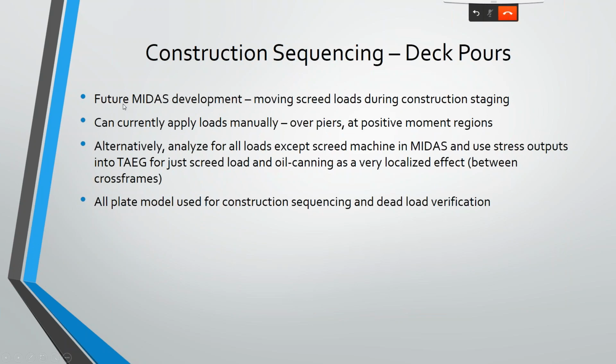All right, future Midas development may include, this would be something for our Midas friends, moving loads during construction staging for the screed loads would be wonderful. However, you can do this manually right now. Typically, I'm looking at that over the piers and over positive moment regions, the worst case locations, wherever you have the worst case positive moment, worst case negative moment during construction, probably going to be your most critical